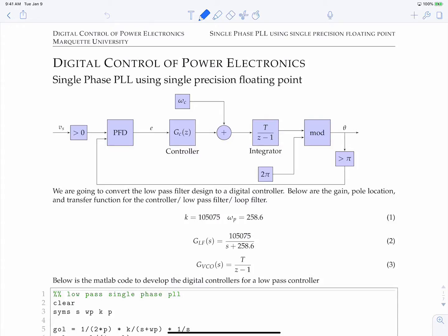The same goes for multiplication, addition, sine, any function that you do on a single precision floating point number. If you don't have a floating point unit, it will incur a large penalty. The other thing too is if you're making a lot of library calls, unbeknownst to the writer, because you need to jump to make these calls, you're going to incur overhead to jump to these libraries to actually do that. So that adds even more instructions. You've got to save the stack, restore the stack, jump, and the delay line in the cache, the cache line, the processor needs to get filled up. So you incur a lot of loss of speed and efficiency. So when you're using floating point, make sure you have a floating point unit on your processor in order to reap the benefits.